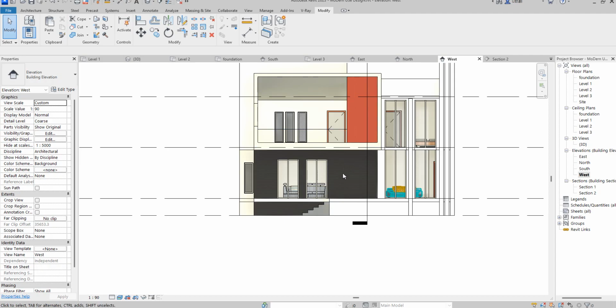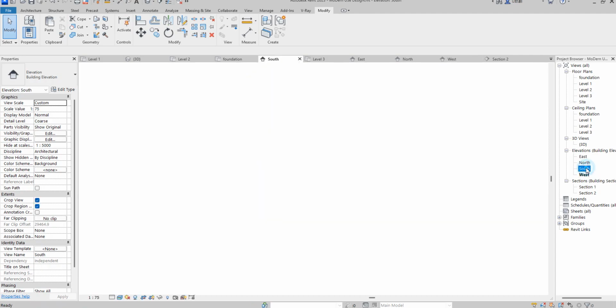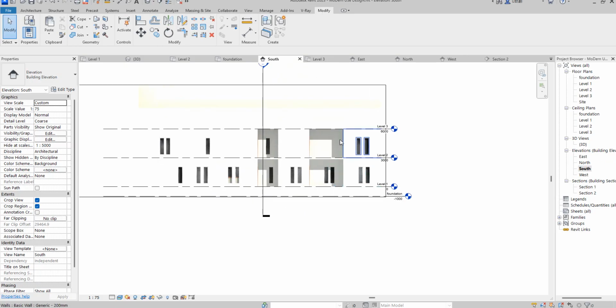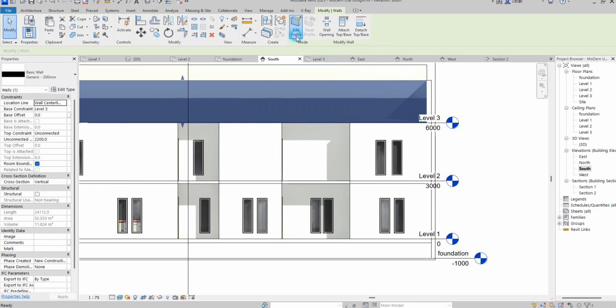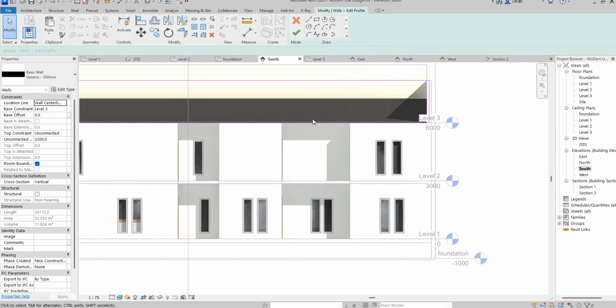But before, there's other things that you can add to this, but let us go to the other part of the elevation and do the needful, arrange them well. So let's say start elevation. Like this, you can't have this or this one in this level. So I'm going to say edit. What I need is to break this and break this. So click here, then draw. Do the same thing here too, then draw.